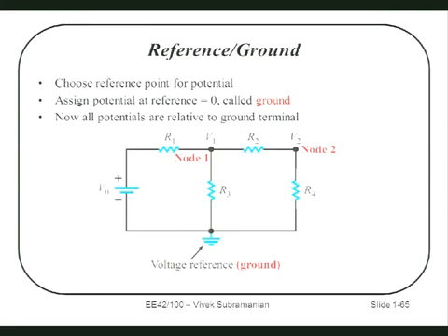So it's all relative. This is the point. Knowing the battery's voltage is useless unless I have a reference. It doesn't matter what that reference is. I could choose to call it 100 volts. I could choose to call it 50,000 volts. It doesn't matter. But to make our lives easier, so that we don't have to add 100 or 50,000 to every number, we typically will pick one point and call it 0. It's often easiest to pick the negative end of the battery and call it 0.